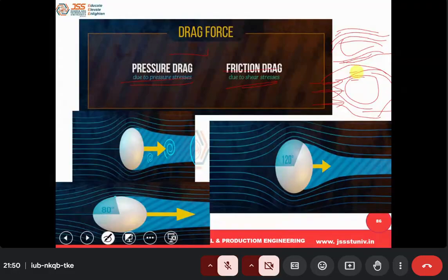Aerofoil or it may be in the ball. And in the ball you can observe here the flow. Which one will take up the very smooth flow without separation? Separation, in the sense, is this shaded area. This is called separation. You can see there is no flow here. This is called flow separation. The flow is going to be diverted.